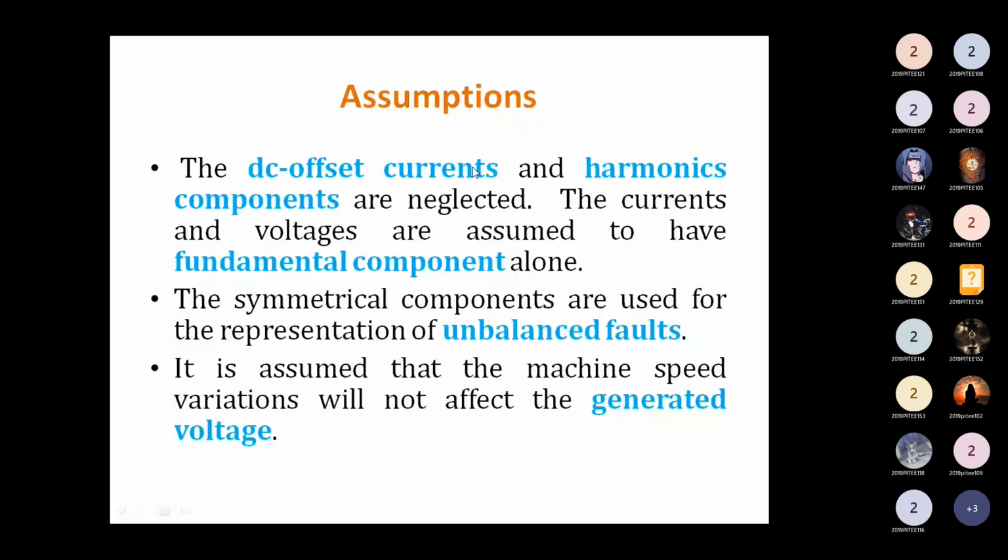We don't consider any first order, second order, third order harmonics here. The voltage and the current should be fundamental. So the first cycle we are going to consider. In the second assumption, symmetrical currents are used for the representation of unbalanced faults. So we are trying to evaluate only the unbalanced faults.